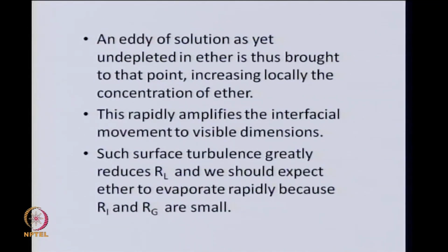What it implies is that along with the surface movement there is a movement induced in the liquid underneath, and if there is a movement within the liquid, clearly the resistance for solute transfer in the liquid phase, that is RL, will also be greatly reduced.